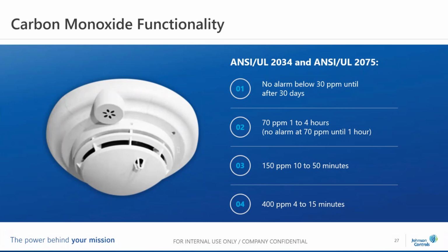Well, what UL has allowed us to do, and many of us manufacturers came around the table. I do a lot of work with NEMA, National Electrical Manufacturers Association. I actually chair the life safety section. And we, being Gentex, System Sensor, Honeywell, Siemens, Simplex, Autocall, we all worked with UL, and we said, look, there needs to be a way for us to test these devices. Customers aren't going to allow me to come in, inject 400 parts per million of CO into their device, wait for at least 4 minutes, maybe 10 minutes for the device to go off. It's going to take me forever to test all the devices, and nobody wants this much concentration of carbon monoxide in their atmosphere.